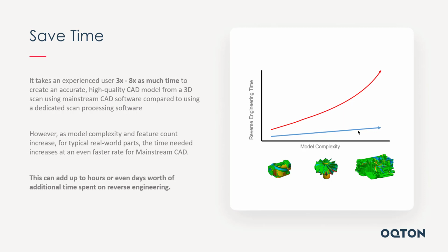So finally, I'll get a lot of people asking me, look at my parts. Do I really need a 3D scanner and software like this to reverse engineer my parts, right? Sometimes there are people that have an application. It's kind of right on the line, right? And this is kind of where I go with that question: how complex is that part? If it's just a 1, 2, 3 block, obviously I can measure that with a pair of calipers and model it in CAD faster than I could even unpack my scanner. But as the complexity increases, the more time you're going to save.